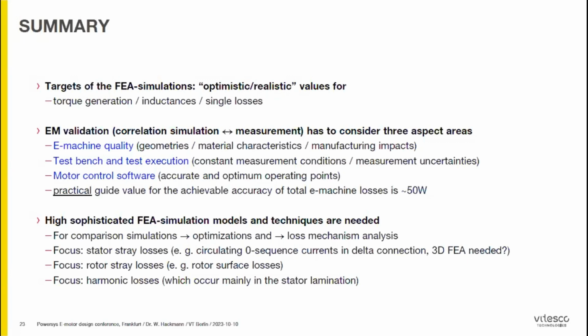Yeah, so skin effect in the stator winding, this factor Kr is dependent on temperature, but also on saturation. This you can see, so it's dependent on the ID current. This you can measure, and this is included in our sequence.